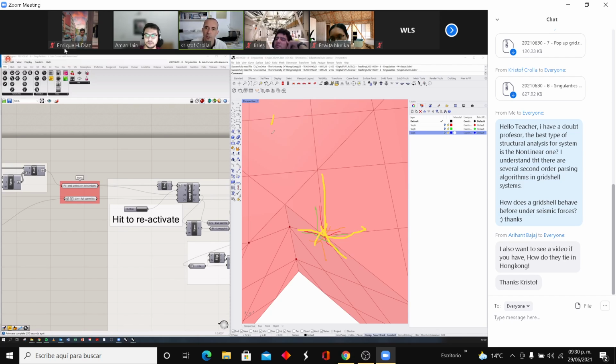So there's basically two things that I start with. A bag of points, which are my live points, and then a bag of curves, which are all the curves that I have. And the first thing I do is I take my first point, which is, say, this one. I identify from this list that I have here, which curves end up in it. Then I join them based on the way that I want to have them joined. And then the four curves that I had originally in the list are being replaced. So these four curves are being removed and replaced by the newly joined curves. So my curve list is gradually shrinking in size because curves are being joined one point at a time.